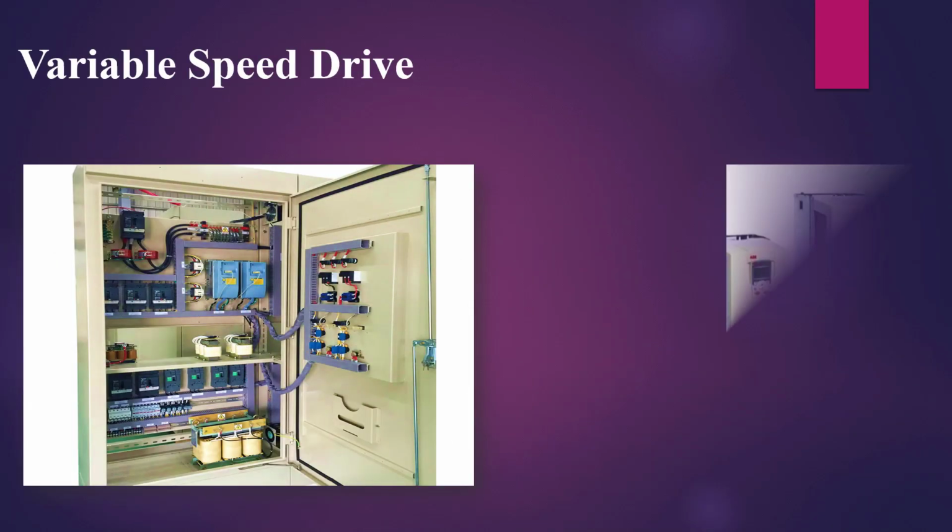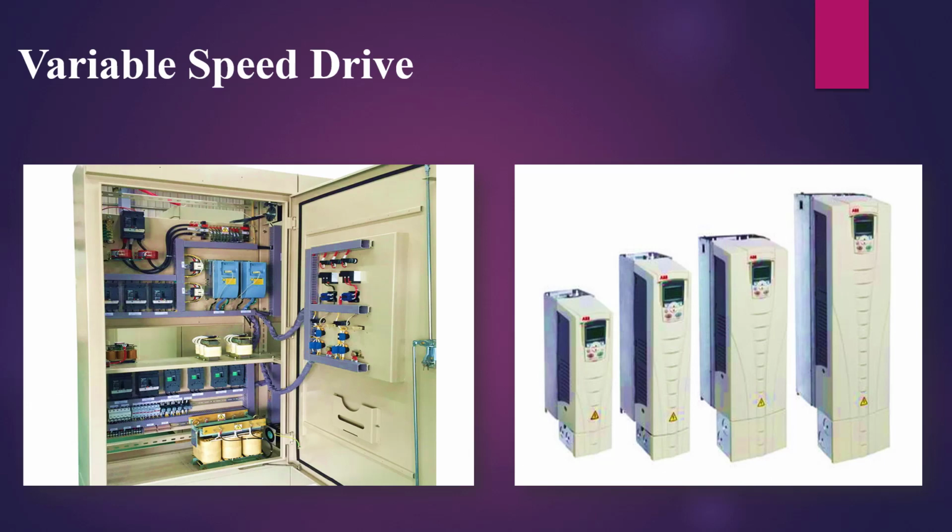A variable speed drive is more efficient, but there are a number of other benefits to consider. For instance, with variable speed drives, starting and stopping operations can be smooth and perfectly controlled. Slow starting also minimizes the inrush currents that often accompany a motor suddenly starting. Inrush currents cause voltage sags that can have damaging effects on the motor and other affected equipment.